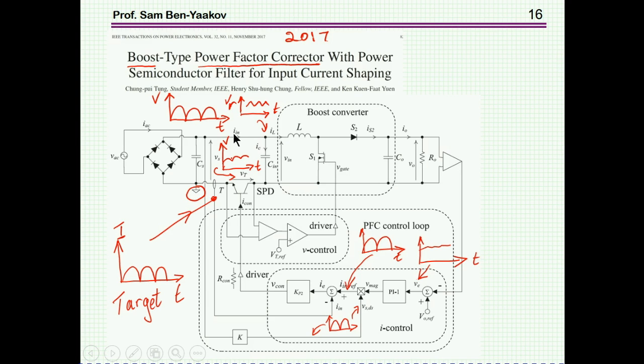By this, it will reduce the voltage across this transistor. So whenever the voltage goes up, this turns on and reduces it. So this actually controls the operation of the MOSFET, the switcher, so as to maintain a maximum value of voltage across this transistor. Very important for lowering the power dissipation.